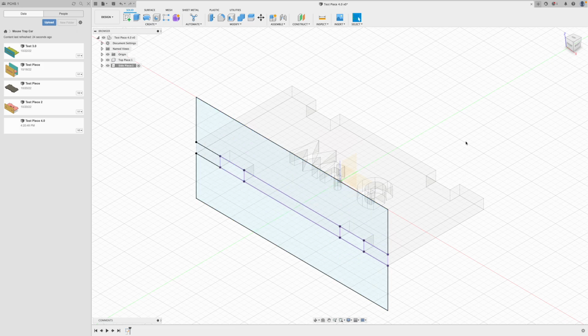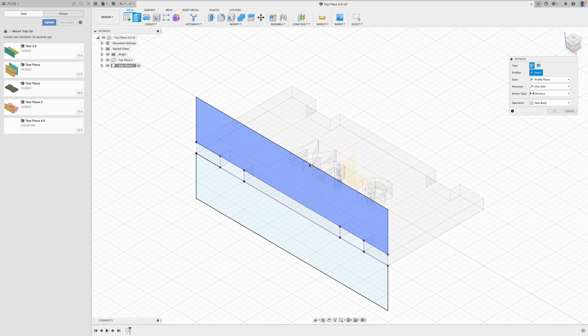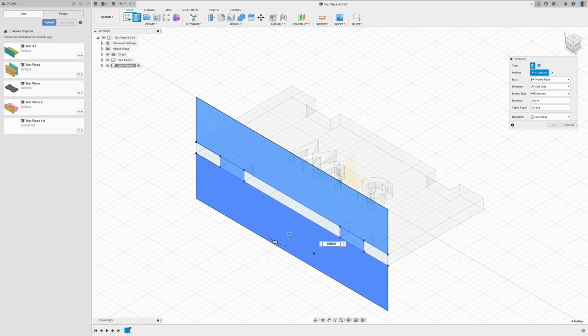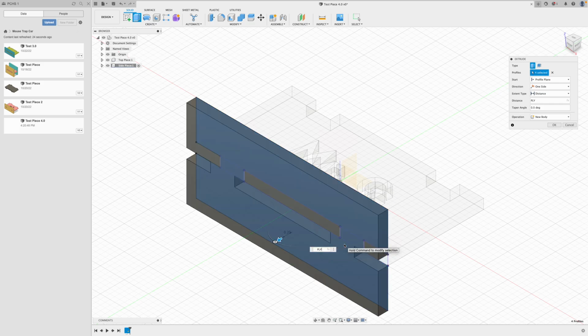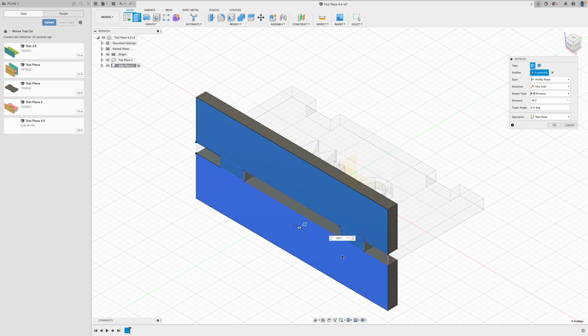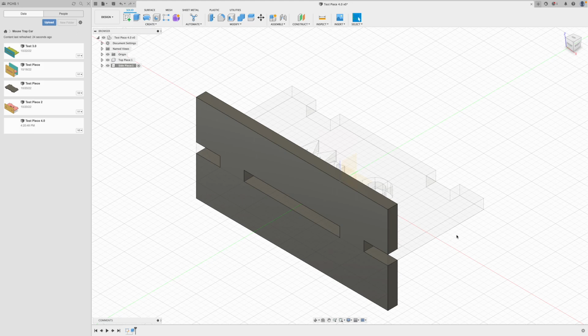So I'm going to escape actually and go extrude, E for extrude, select my layers. 1 selected, 2 selected, 3 selected, 4 selected. And what I'm going to do here is project this inward. And we're going to do this by a distance of, if you guessed it, ply, P-L-Y, enter. Oops, we need to go negative ply, because we're going the opposite way there. Bam. And then click OK.